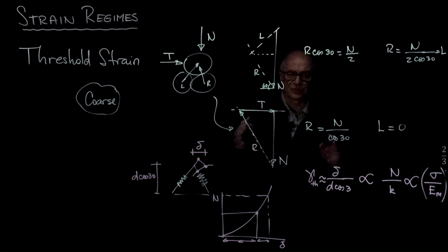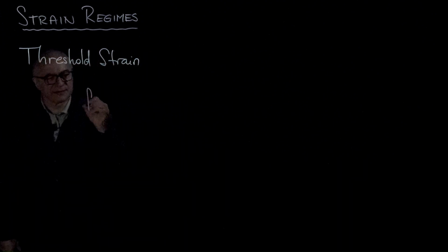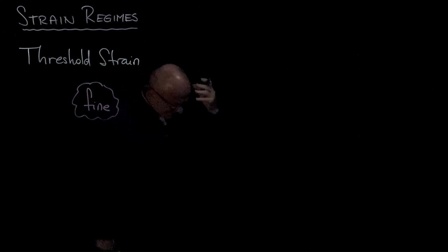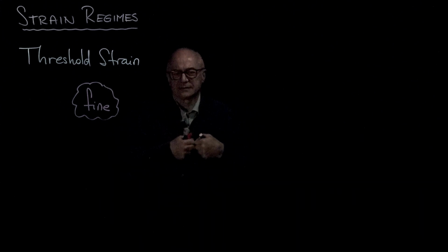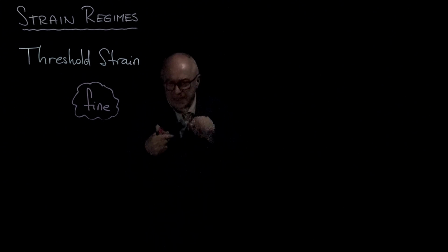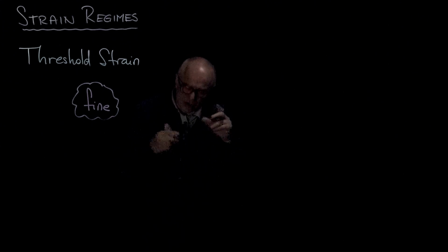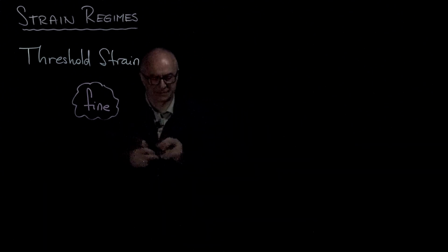Wonderful work done by Vucetich and Dobry and by some of our Japanese colleagues on the threshold strain for sands. Now, what about in fine-grained materials? In this case, we have a dilemma because we cannot think of solid-to-solid contact. In reality, there is an adsorbed layer around every particle, regardless of the size, but that adsorbed layer is very small compared to the particle size in sands, but becomes very relevant in clays.